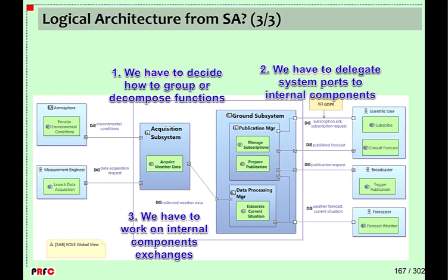In this new video, we are going to cover a somewhat advanced topic called component port delegation. To illustrate this, we will take an extract from my Capella training with the EOLE model, also presented in the first book on Capella. The example is located at the level of logical architecture, but could also have been located at physical architecture level. Remember, delegation of component exchanges is an important and difficult topic related to encapsulation and modularity of your model.